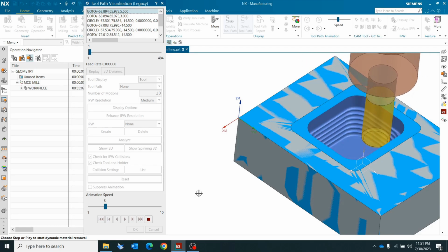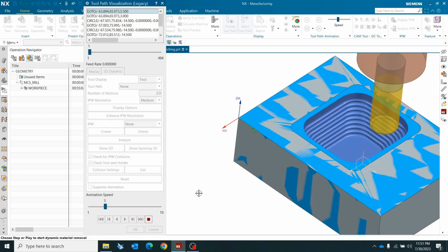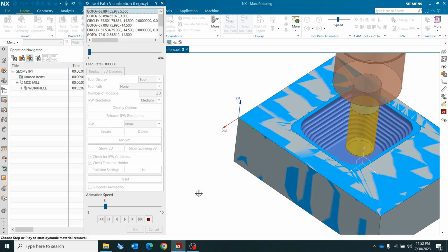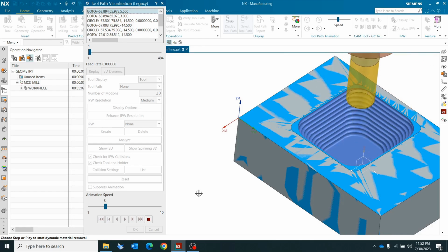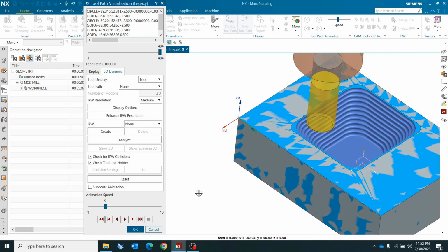With respect to the last operation, it is removing more material. If you keep bottom up cutting, it is a very big advantage. Like this, you have to do adaptive milling operation if your cutter is a carbide cutter and it is having side cutting edges. You don't go for HSS cutter and inserted cutter for this particular operation.